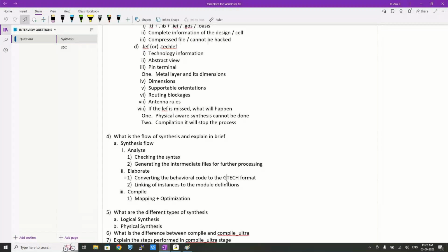Linking will fail. So if there are any hard coded instances in your RTL code, the equivalent libraries have to be provided. If there are none, elaborate will pass, by converting every instance to the RTL global files, and it will be able to map or link it.